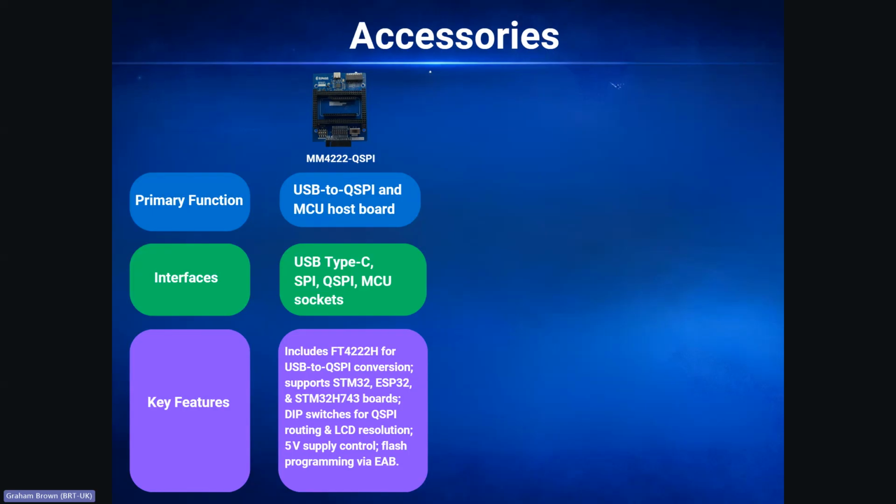This includes an onboard USB to SPI IC for direct connection to a host PC, allowing rapid development of EVE-based applications. This module includes a pin header for a number of popular MCU platforms as well, such as the STM32 or ESP32, so you can connect these directly into the board and interface them to EVE.